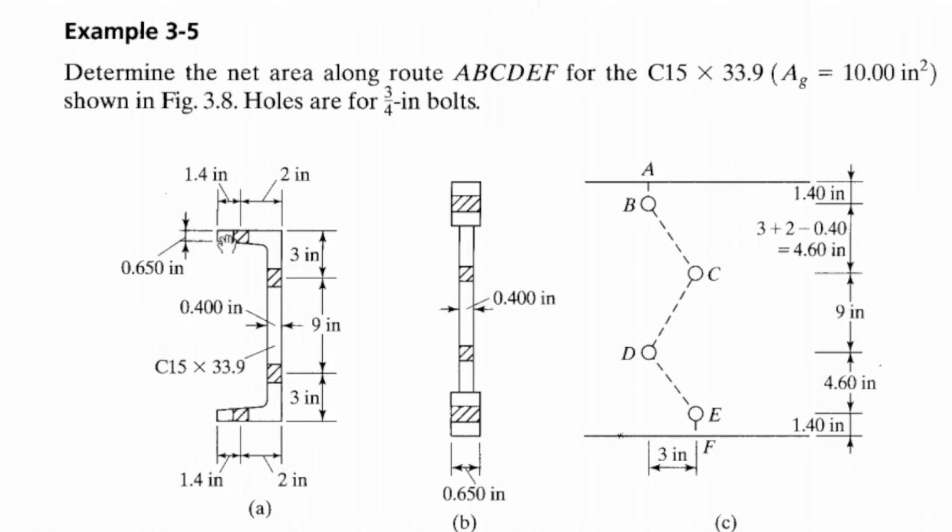Okay. So what we did is to straighten up. So turn this 90 degrees up and turn the bottom flange 90 degrees down. That's why it looks like this. So this section looks like this. So meaning to say, from this center to this center, these are 9 inches. So from this to this, 9 inches. Okay?